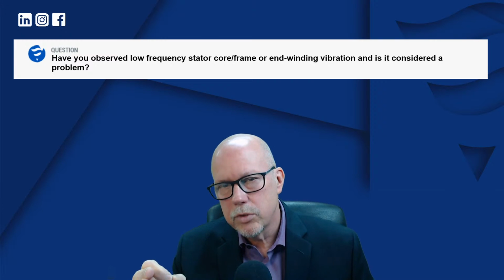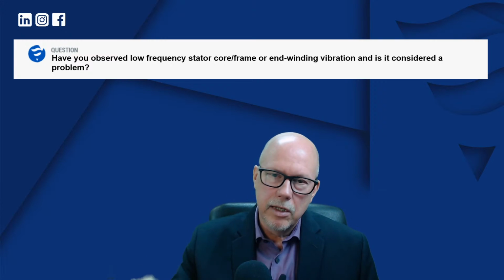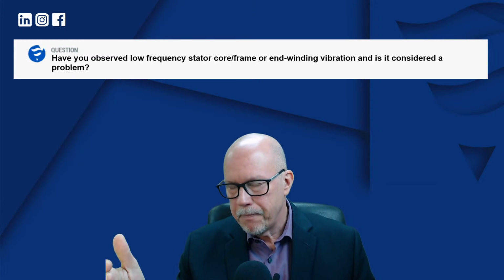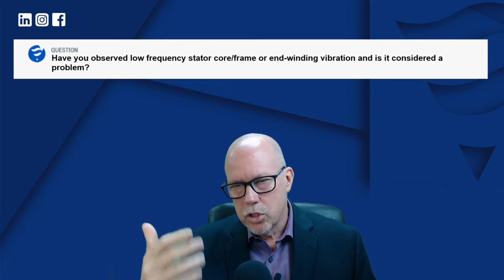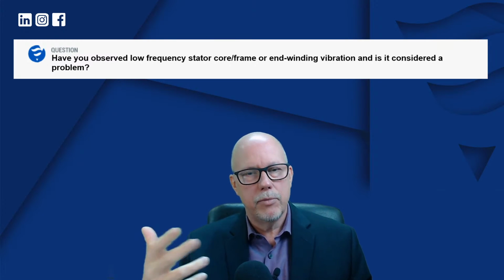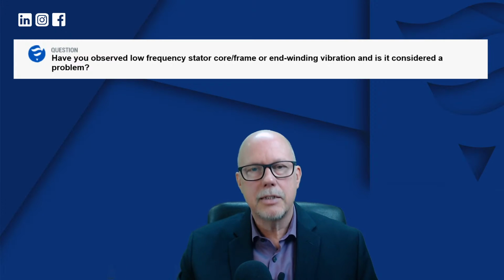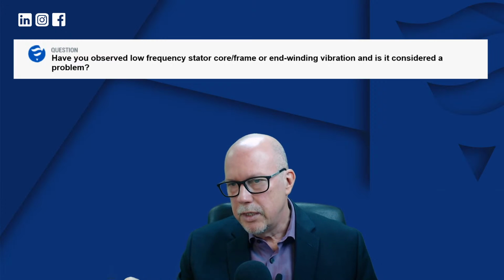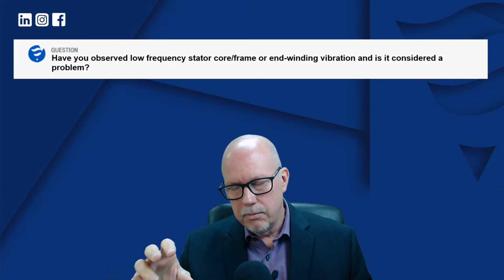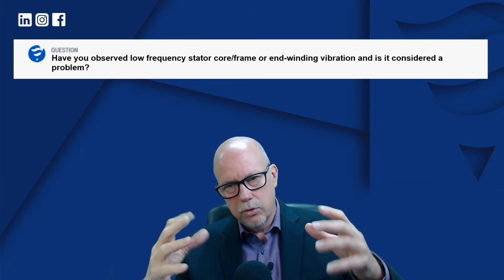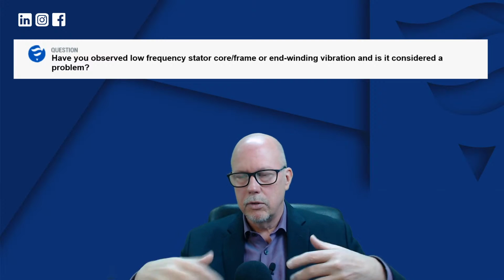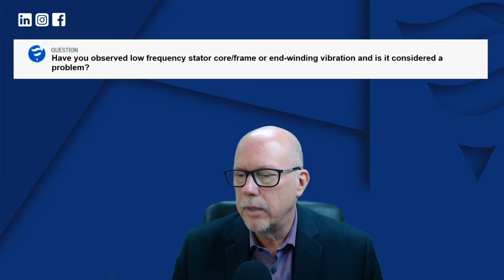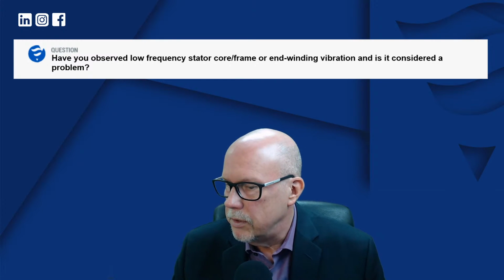So the 120 hertz was normal, but they had all this stator core movement banging on the foundation that we were able to pick up, and it was showing up, but nobody understood what that vibration was. And that last sensor on the core gave us the information we needed. The end windings were not moving in relation to the core. The whole core was moving. So they went in there and did a better job of fastening the core and the frame, and the problem disappeared.